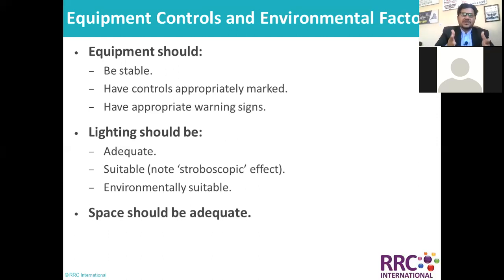And bringing new machines means the area would be more congested. The accumulative sound will go up. That means you can't meet the legal limit of 85 decibels; it would be so high. So you have to provide the right set of PPE, or it might be a terrible violation of PME regulations, like the Presidency of Meteorology and Environment of Saudi Arabia. And if you are working with Saudi Aramco, the EPD, Environmental Protection Division, or even LPD, they can catch it. It's not acceptable. That is why it is clearly mentioned that the space should be adequate.